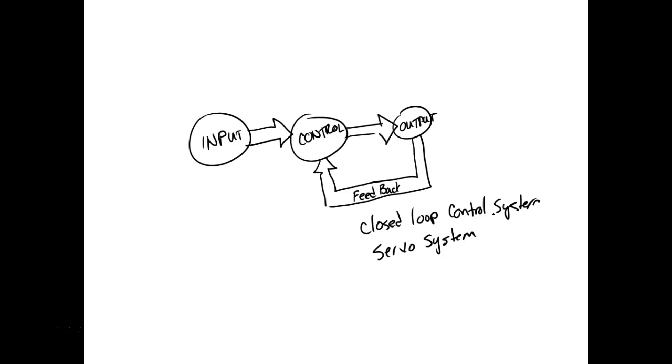If we don't have a piston over there in the back, the robot will swing over there, go down, and close its hand. But that robot over here doesn't know there's a spring there. So if you don't go out there and move the spring out, what does it do? You reset it, it'll go up there and do what? Grab one, come over and do what? Set it down right on the top of it. So that system there is open loop between the robot controller and that right there.